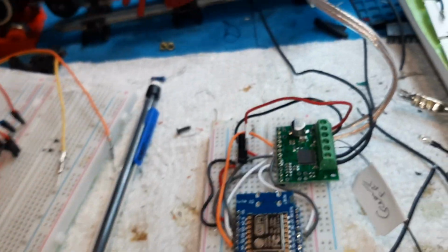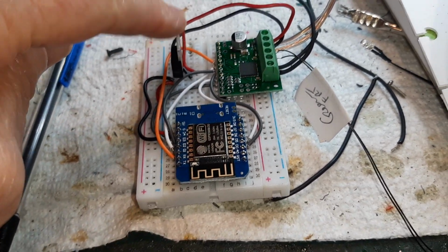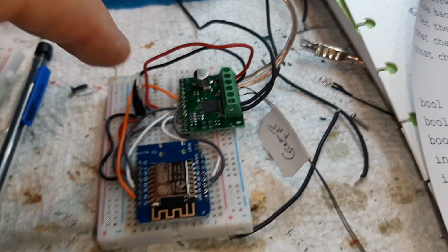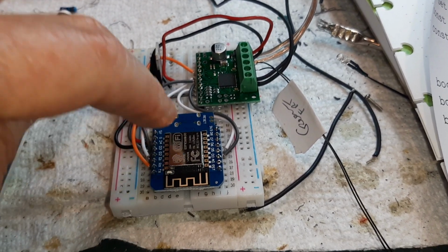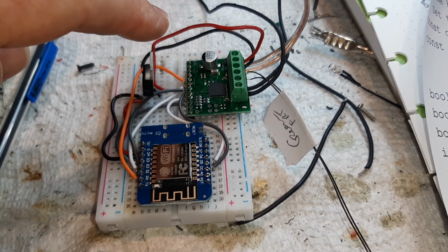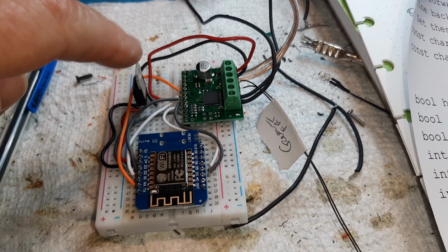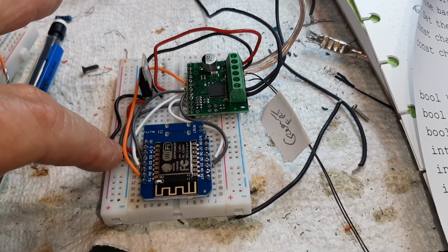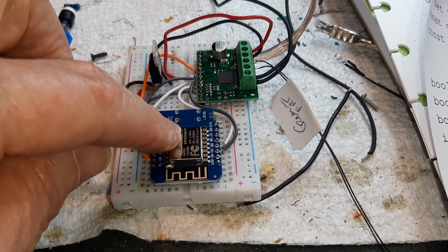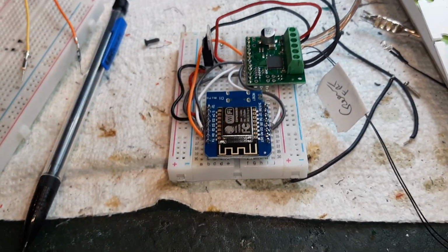Okay. The one thing that's a little tweak is I have a 7805, because this guy can actually handle up to 40 volts DC. Well, this guy can't. He needs 5 volts. So this 7805 is a 3-pin transistor that you can feed in voltage and it will drive out only 5 volts. It's engineered to regulate to 5 volts, period. So it will send 5 volts to our microcontroller reliably and accurately, regardless of what's on the input.